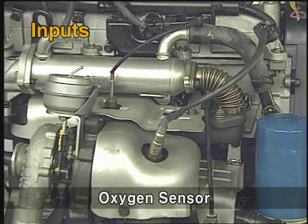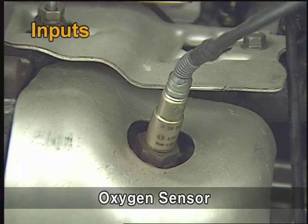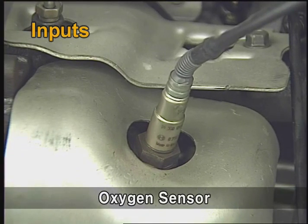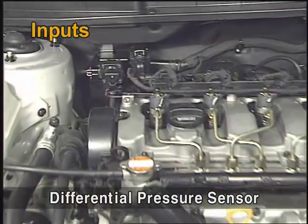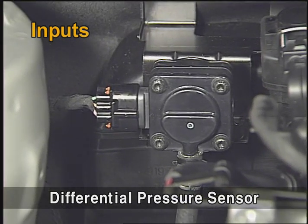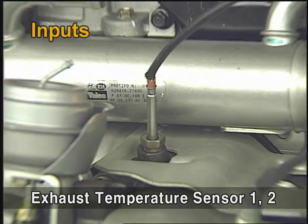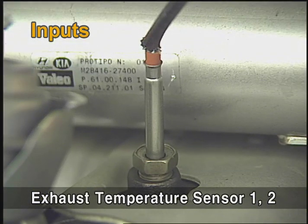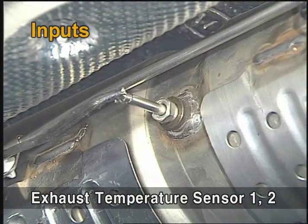the boost pressure sensor for controlling the VGT, the wide-range oxygen sensor for detecting the oxygen density in the emission from the exhaust pipe and for controlling the AF ratio, the exhaust gas differential pressure sensor for measuring the amount of the PM gathered into the CPF and for sending its data to the ECM to regenerate the CPF, the exhaust temperature sensor 1 and 2 for maintaining the temperature in the CPF to 650 degrees Celsius at CPF reproducing,